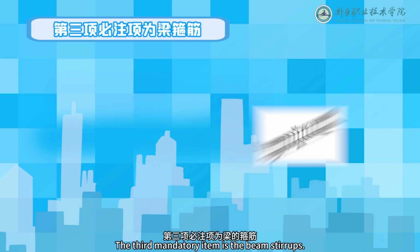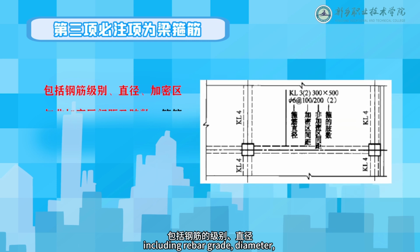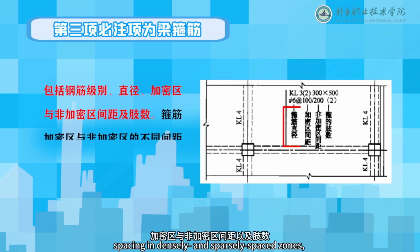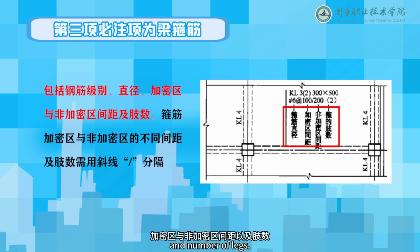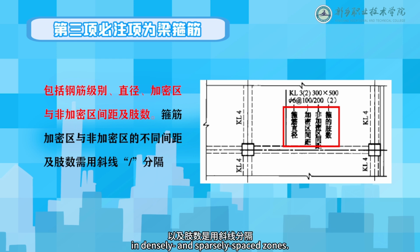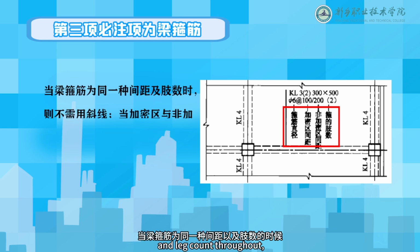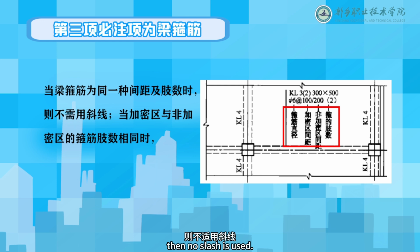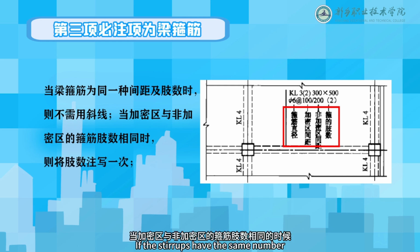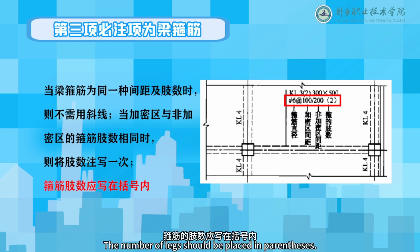The third mandatory item is the beam stirrups. Details of beam stirrups are shown in Figure 5:1, including rebar grade, diameter, spacing in densely and sparsely spaced zones, and number of legs. Use a slash to separate the spacing and leg count in densely and sparsely spaced zones. If stirrups have the same spacing and leg count throughout, then no slash is used. If the stirrups have the same number of legs in both zones, then write the leg count only once. The number of legs should be placed in parentheses.